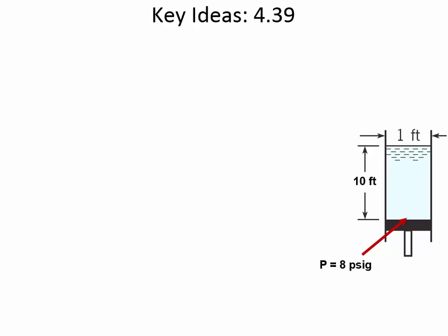First of all, what does psi stand for? Pounds per square inch, and so it's lb per in squared. All right. Now, our distance of 10 feet suggests that we should think about pressure not in terms of inches, but in terms of feet. So how do you convert pounds per square inch into pounds per square foot? 12 inches per foot, right.